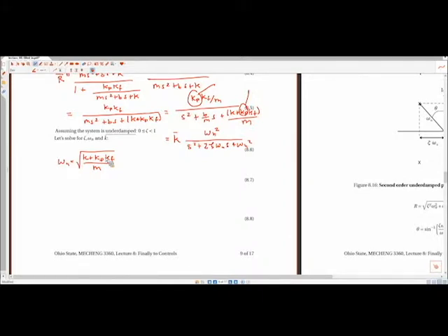That would be changing our parameters K, M, KF. That would cost a lot of money to do. Or, because we're using controllers built into this, we can simply change this parameter KP in a line of code, in about a minute, and that changes the behavior. If we increase KP, we see that the natural frequency of our system increases. So K, KF, M are all fairly difficult to change. KP can be changed with a keystroke, really easy.